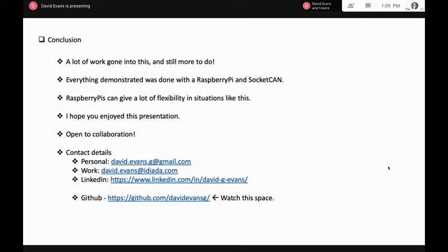I mean, there is a kind of a latency concern or bus speed concern at some point, especially if you're doing something like a man in the middle, where you're taking a message from one CAN bus and you're trying to not transmit it and instead send your own message. Yeah. So one of the problems I encountered was when I increased the volume on the iPhone. So I used the vehicle's volume up button. That will always, because it's a broadcast system, the radio's always listening. If it receives that request, it will try to turn up the radio's volume.